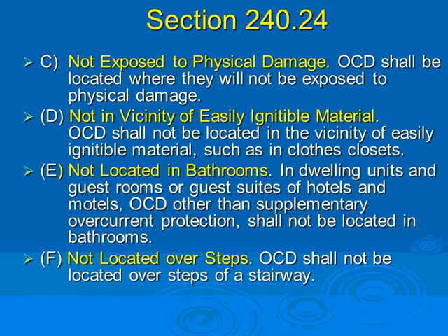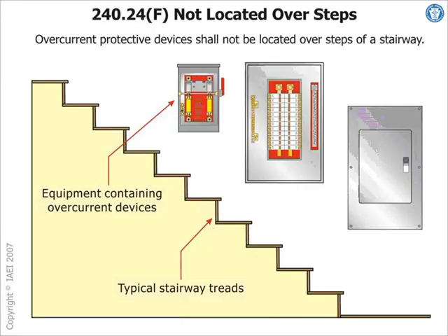No, not located over steps. That came in 2005 or 2008, I want to say 2008, because we're just tired of people tripping. So if you want to put a fused disconnect or circuit breaker over steps, it's a violation of the code here; it has to be on a landing. Anybody know why? Because it has to be readily accessible and have clearances in front of the equipment to work on it, and that place is not a proper place to work, right? So it has to be on a landing. So that came in 2000 something.